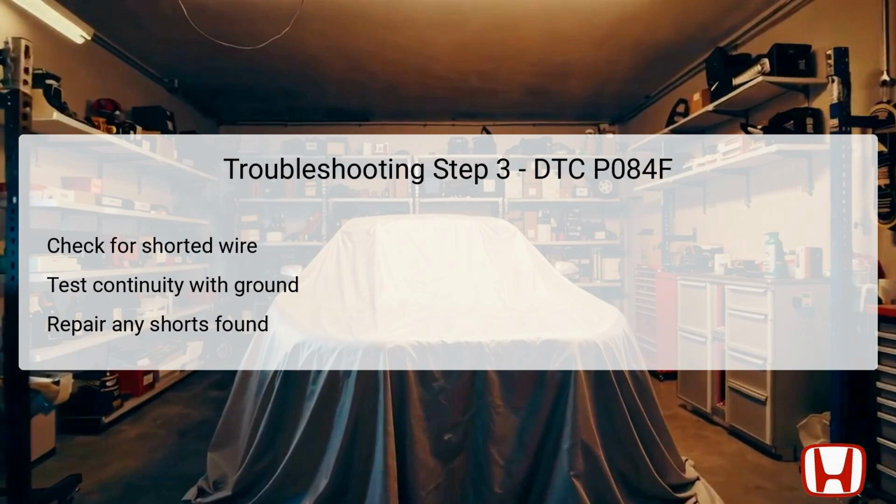This requires that the vehicle remains in the off-lock mode, and both the TCM58P connector and the under-dash fuse relay box connector E should still be disconnected. Once in position, repeat the continuity test again using pin 32 at the TCM58P connector as your first test point. For the second test point, use a suitable body ground.